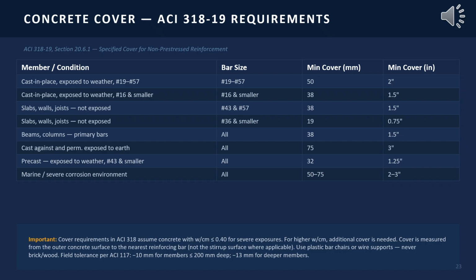I have covered concrete cover briefly in my previous sessions. So remember, it's your first and most important physical barrier against corrosion. Concrete cover, as you know, is the thickness of concrete between the outer surface and the nearest edge of the embedded reinforcement. Getting the cover right on site is as important as getting the mix design right, and it's often where most of the projects in Pakistan fail.